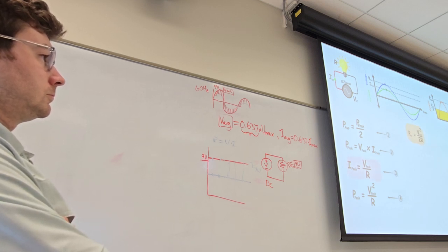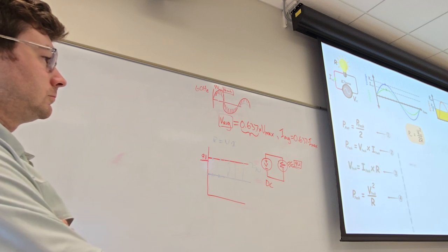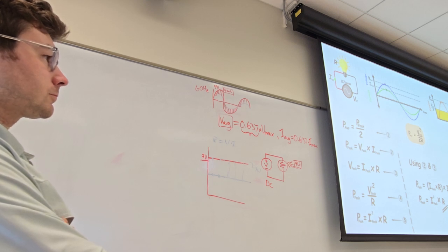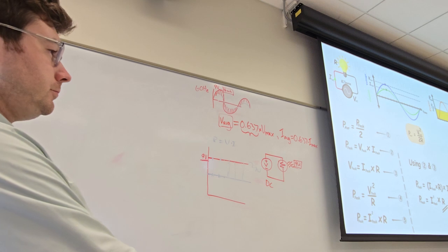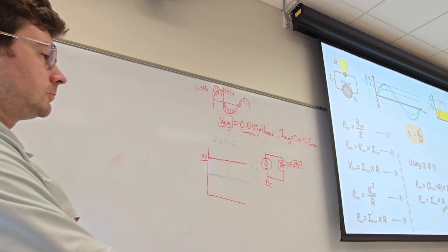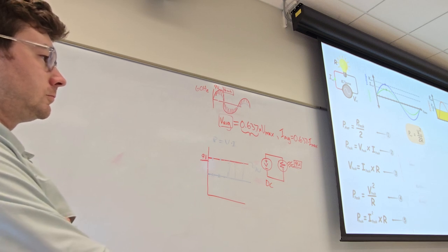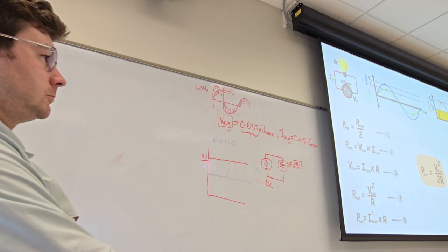Let's revisit equation 3, rearrange it, and express the peak voltage in terms of peak current and resistance. Utilizing equations 2 and 3, we can then articulate the peak power using peak current and resistance, establishing our fifth equation. Now, employing equations 1 and 5, we can formulate the expression for average power using current and resistance. The average power of an AC power circuit is equal to the squared peak current multiplied by the resistance, divided by 2. Indeed, these two equations play a crucial role in understanding RMS.